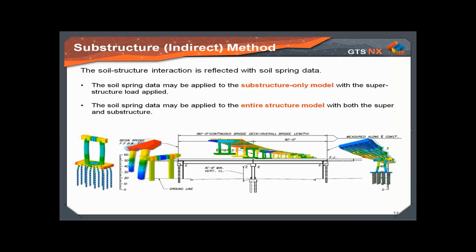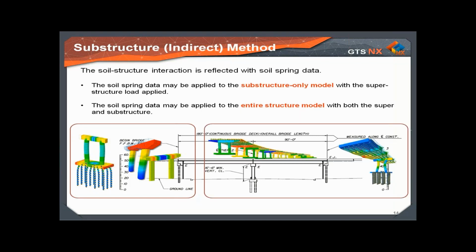However, when we have to consider the soil structure interaction, it may affect the superstructure as well. Therefore, we have to understand that with these substructure only approaches, we are working with broken components of the whole system in reality, especially if we are dealing with seismic analysis. The second, the entire structure together approach, is the more common and more accurate approach, taken if an engineer is using an analysis tool such as MIDAS Civil or MIDAS Gen.